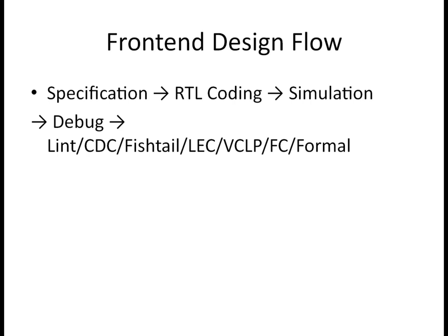Next is your RTL verification flow. Here, the first thing is that setup wise it should be clean. I mean the constraints should be correct as per the RTL: the clock, the RTL port information, everything. Whatever is mentioned in the constraint should match the RTL. Then only setup wise can we claim to be correct.